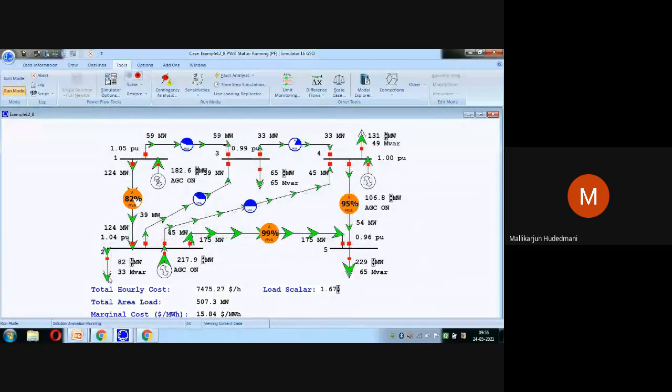For the change in demand, they must generate adequate megawatt, sharing the disturbance or load in proportion to their capacity and characteristics. That is one important characteristic that we find from power system operational control. So as the load changes, the generators identified to respond will respond in proportion to that change in the system. You can see this. Suppose I increase this load, to show how the generators' output will increase. Let's see here, I will increase the load here. Can you see there? There is an increment of megawatt going.